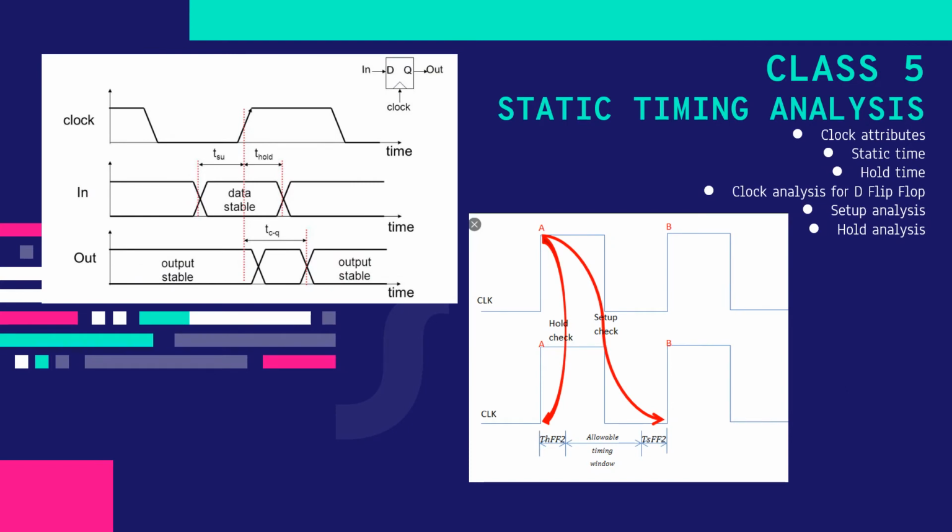In class 5, we covered static timing analysis. We first began by learning how in the 70s this was performed with SPICE simulation. In the 80s, timing was included in Verilog simulation to determine if the design was sufficiently fast. But two problems were present with either approach. One is that analysis was only as good as the simulation, and logic simulations were 5 to 10 times slower. In static timing analysis, which is more comprehensive, one calculates the time for every component and every path.